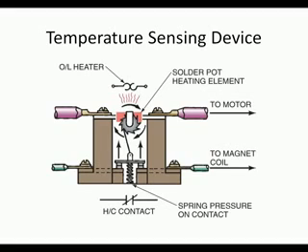Temperature sensing devices used in motors are bimetal elements. These devices are called heaters, wired in series with the load. The heater is exposed to the current draw of the load. The bimetal warps and opens as it gets too warm. The open bimetal de-energizes the starter on the holding coil.